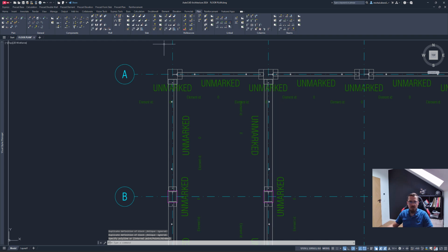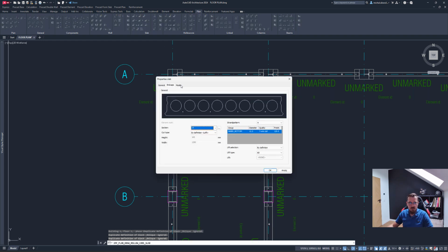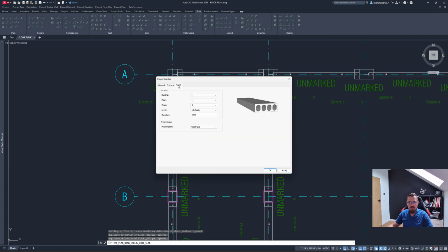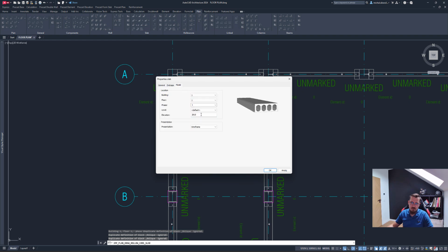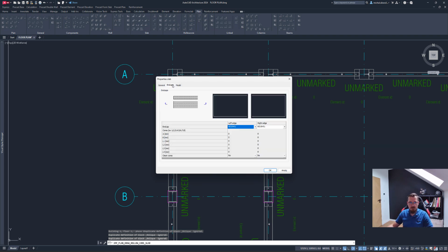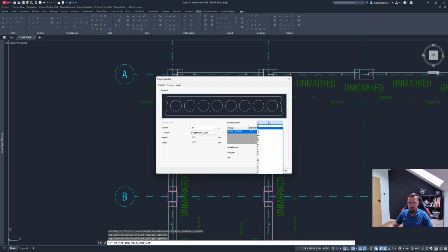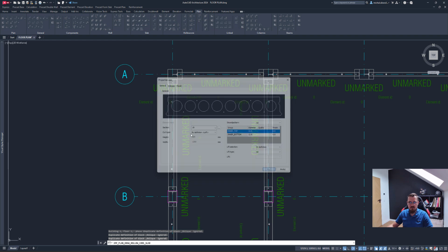Oops, let's go back actually, and then specify the height at which I want that hollow core. Okay, my math, will it be right? The height of that is 185. Okay, we might need to lower those hollow cores to sit flush on the beams. We'll do that after the fact, because we can still move the elements in the space after we're done. So let me just select that again and select the strands, and let's accept that.